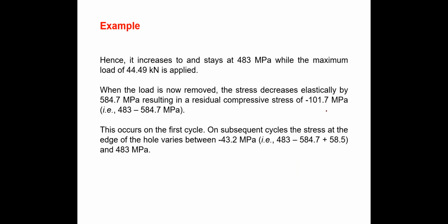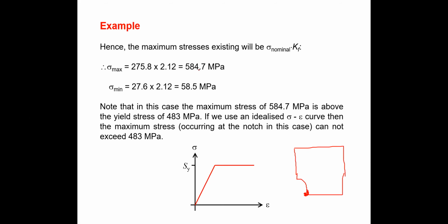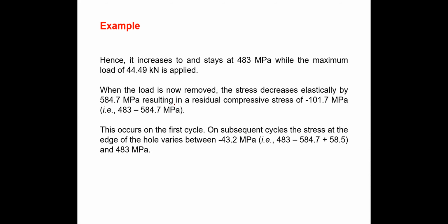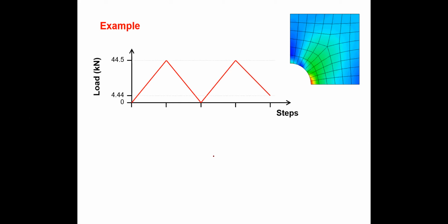So with this slide, you can see 584.7 and this value, the difference between these two is 44.49. It will stay inside as residual stress, and when we apply the compressive cycle, with this diagram you can see we can't go beyond this range.